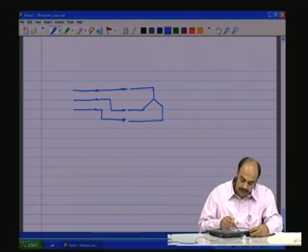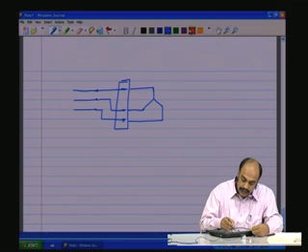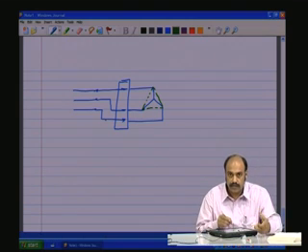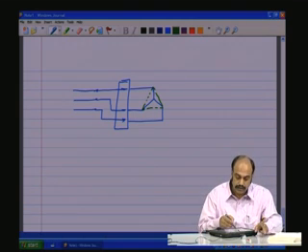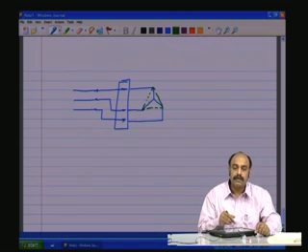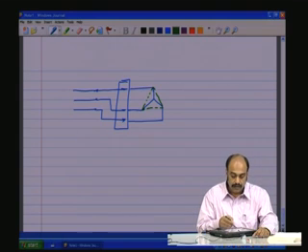Then we have a switch mechanism such that as the motor has picked up speed, we put this in a delta fashion such that the winding voltages see the line to line voltages, which is a higher voltage. So in the star fashion you have E line by √3 applied across the phases, and in the delta fashion you have E line applied across the stator coils.